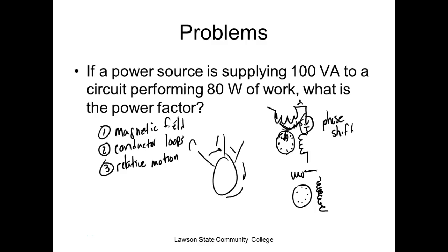You can see these capacitors. A lot of the motors, they'll have big old humps on the outside. Those are what? Those are capacitors. Now, most of your HVAC systems, they'll have two wires that come out, and they use an external capacitor. Now, why they do that is that those things go bad all the time because they're outside. They're outside with all that lightning and stuff like that.